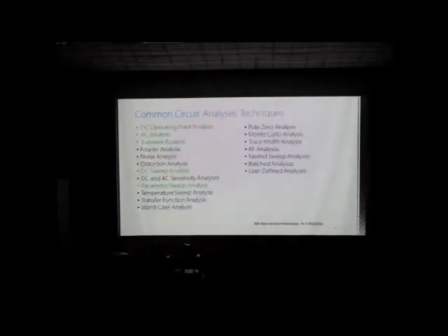Okay, so the next one is the analysis techniques that we need when we're studying or designing. DC operating point, AC sweep analysis, parametric sweep. So these are the things we actually need to learn. This is why we use Multisim. The green highlighted ones are the ones we usually need, but I'll be showing the AC analysis, transient, DC sweep, and parametric.